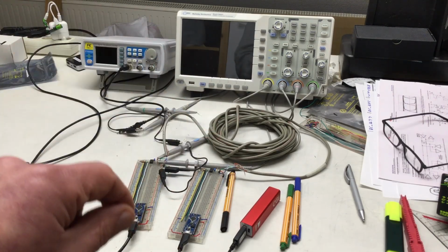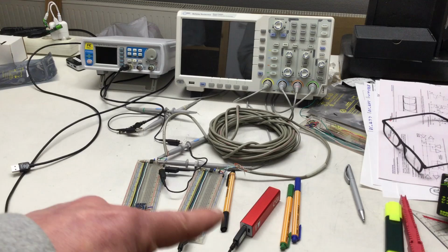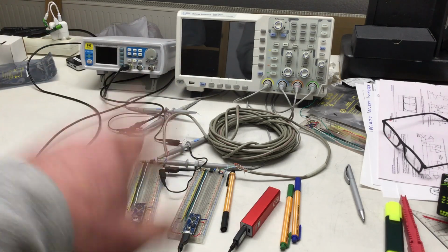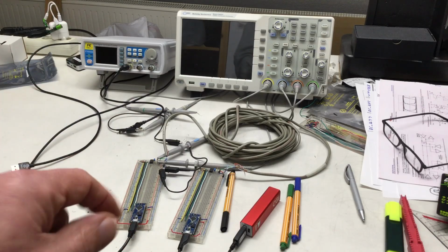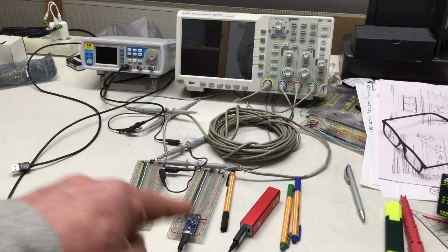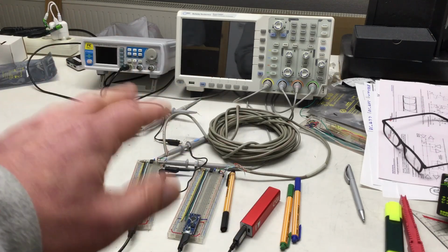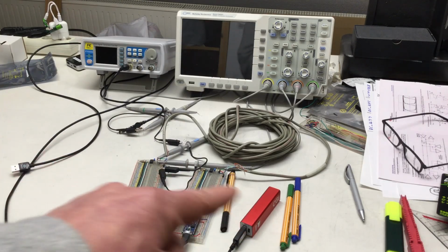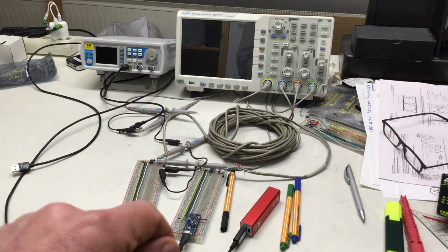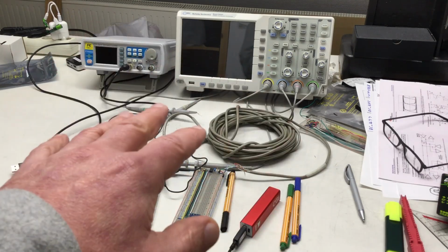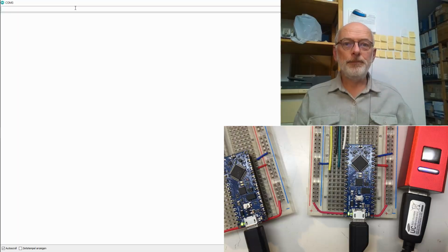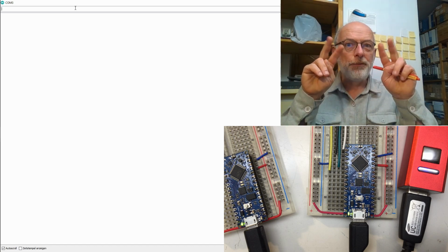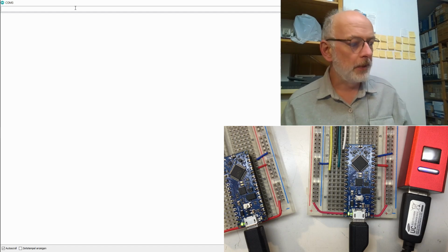However, at the end of that video I told you that the code for our Arduinos contains a fatal flaw and we'll have to fix that. In addition, we just have one master and one slave, but RS-485 is a bus, so we want our master to be able to talk to at least two different slaves. Both we will do in this video. Enjoy! Let's dive right in and explore that fatal flaw in the code we've created in the previous video.